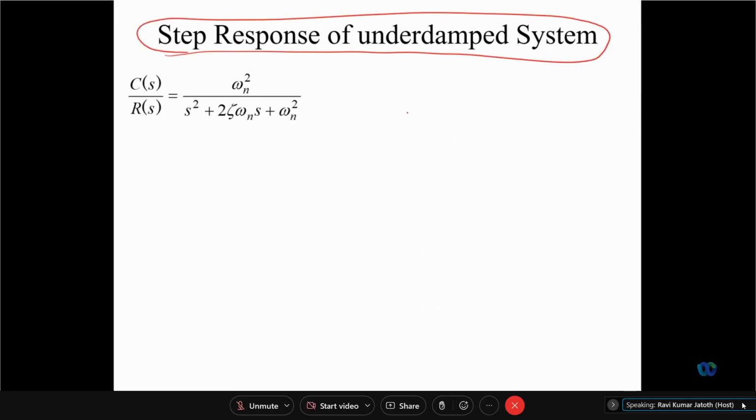For the critically damped system, the roots are real, no? For the overdamped system, zeta is greater than 1. For zeta equal to 1, the roots are real. If zeta is very much greater than 1, are the roots real, complex, or on the imaginary axis? Real, but they are a little bit away from the imaginary axis. So we will consider those cases.